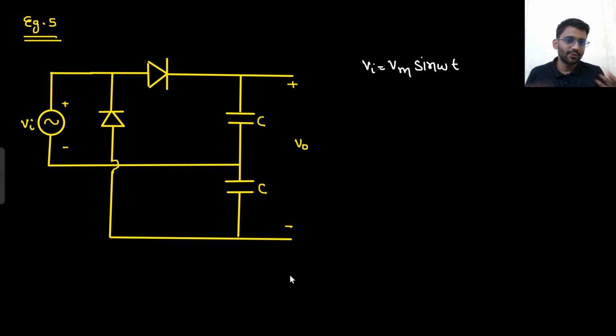So in the previous question, we saw that positive clamper, then positive peak detector, negative clamper, negative peak detector, positive clamper, negative peak detector. All those standard circuits we saw. Here, can you see? Try visualizing it. Look, what if I connect ground here? I assume ground here. Anywhere ground is not given, I can assume ground anywhere, right?